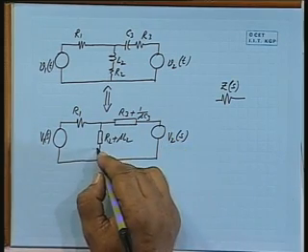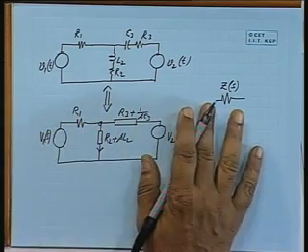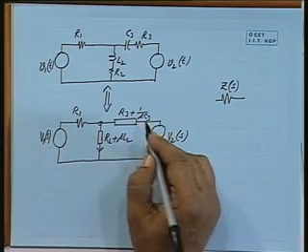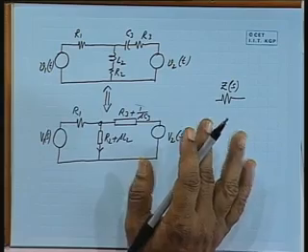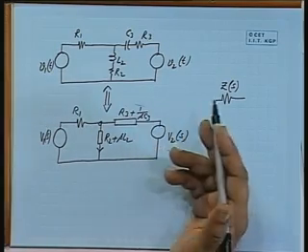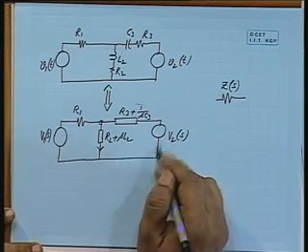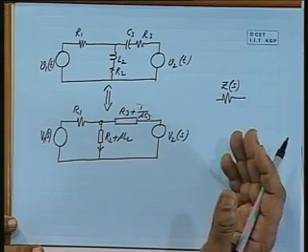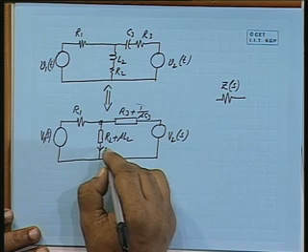Now, for calculating the current through any branch or potential at any node, you can apply superposition theorem, nodal analysis, Thevenin's theorem, any theorem you want, by treating these as simple algebraic operational impedances, treating s as an algebraic operator, and then when you get the expression for current I(s), take the inverse, you get the current i(t). So, if I am interested in the current through this I2(s),